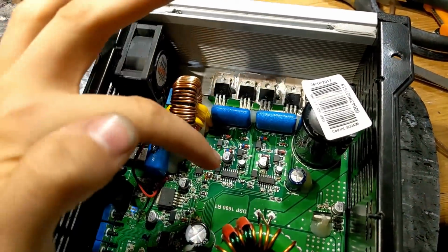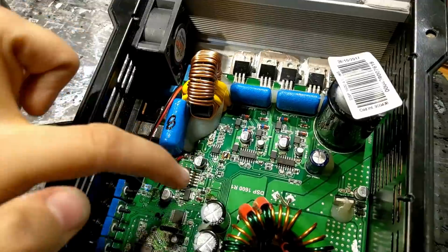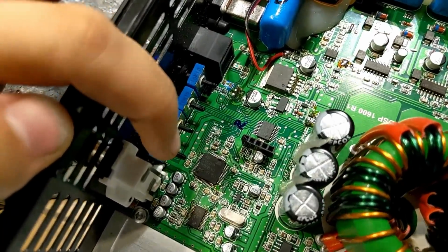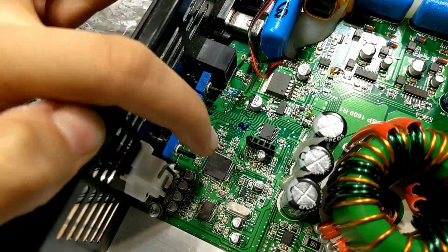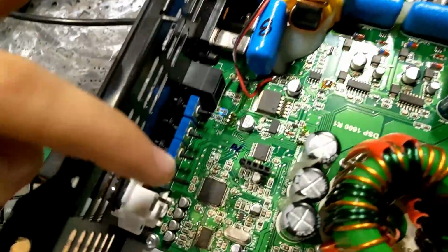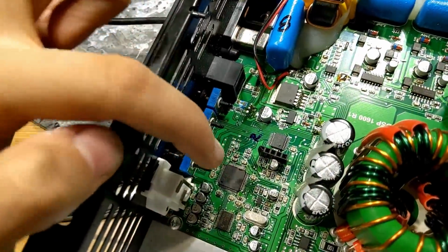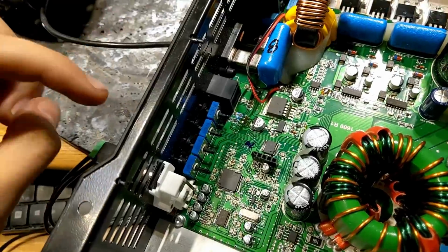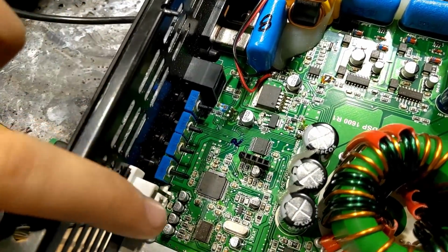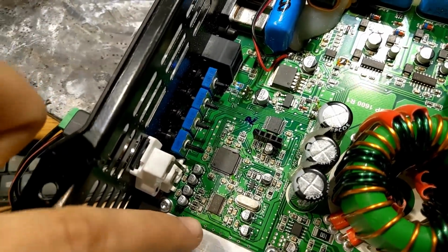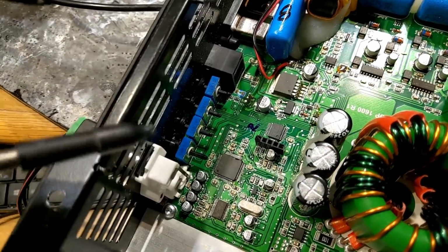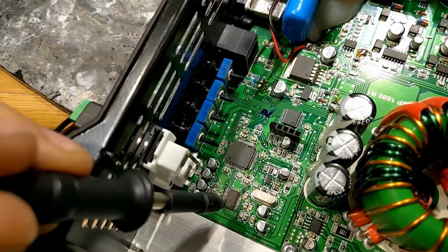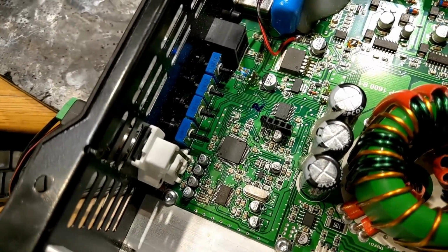So I traced the issue, and the issue actually comes all the way back down to the output of this audio chip here. And I was like, oh right, maybe something spiked back down to this audio chip when it blew, and it's damaged part of the circuit in here. So I replaced this chip. Didn't make any difference. And then I looked a bit further down, and I noticed that actually this half sine wave thing was actually coming out of this chip as well before it went into this one. So I changed this one. No difference. What the hell is going on?